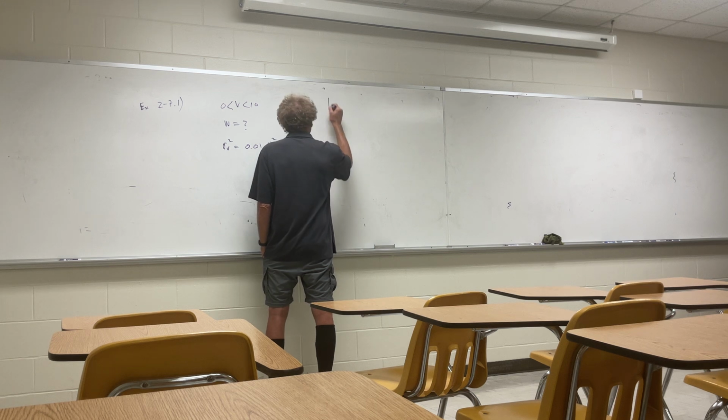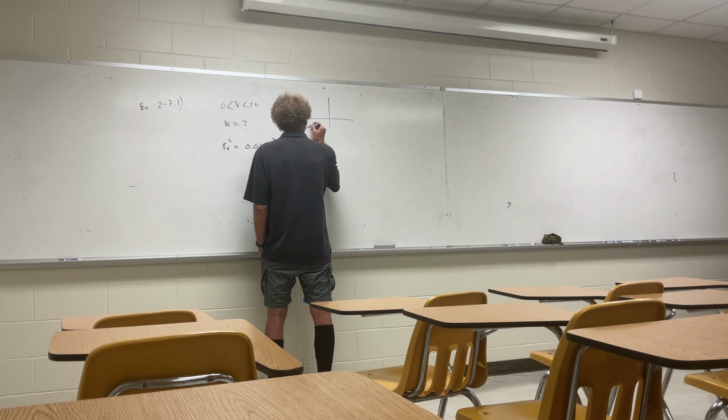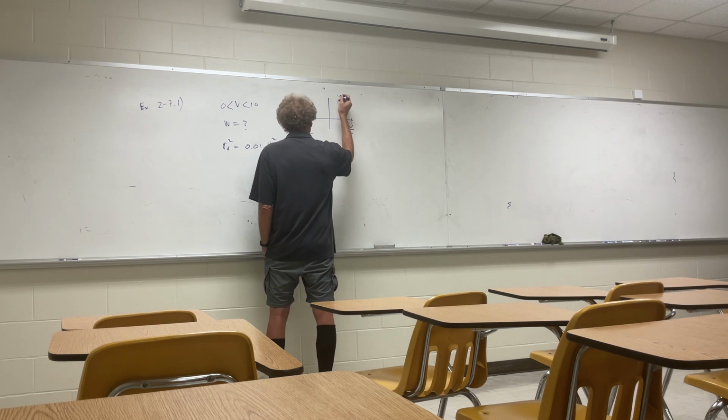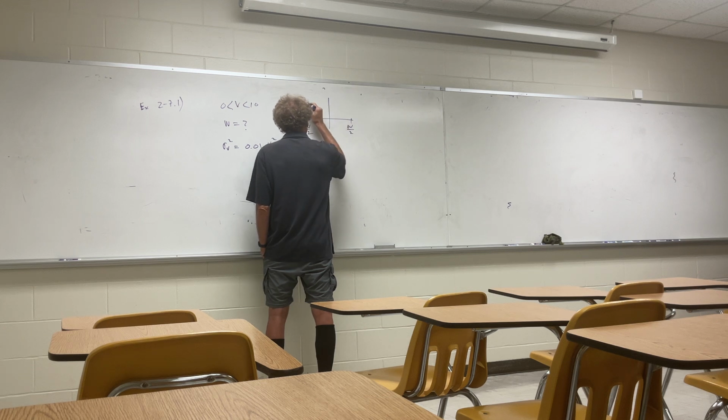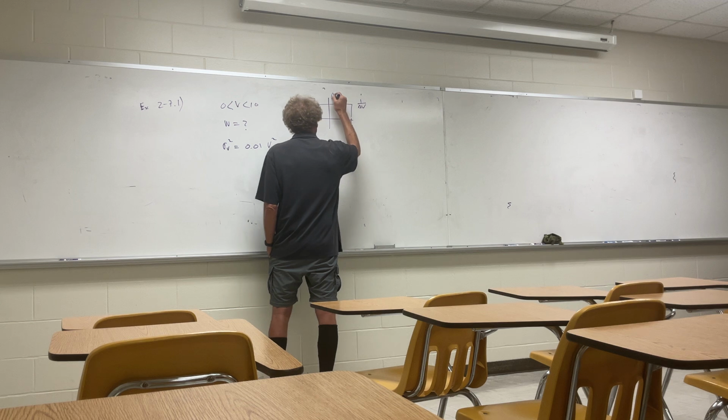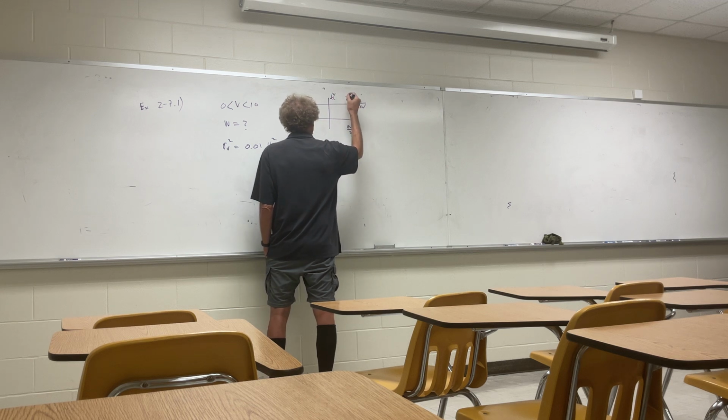For this one, we know, and here I'm going to plot the quantization error from minus delta V over 2 to delta V over 2. And here, we know the height is 1 over delta V. It's a density function of V, right there.